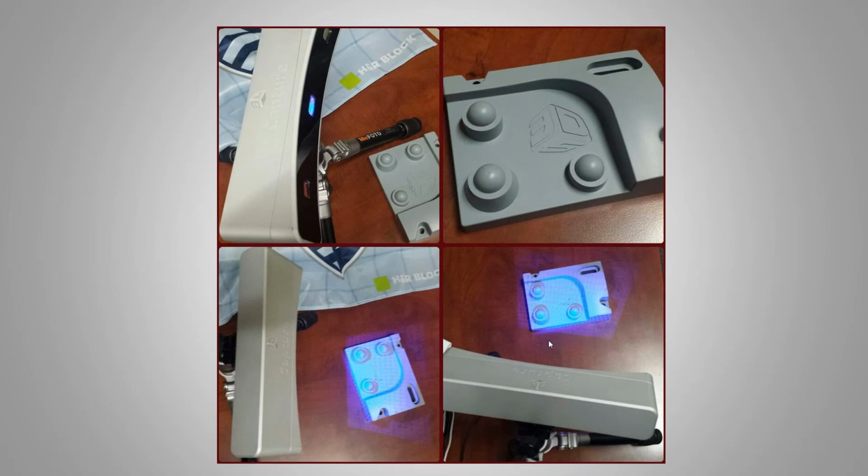You'll notice that the part that we've got is a very flat gray in color. Now, a lot of machine parts we may be scanning may be highly reflective. One thing to note is if it is a highly reflective material, we want to coat it. We here at D3 use a weld check. It's a spray material, an extremely thin layer, that basically makes the object a very flat, almost white in color, which works extremely well for capturing fine detail.